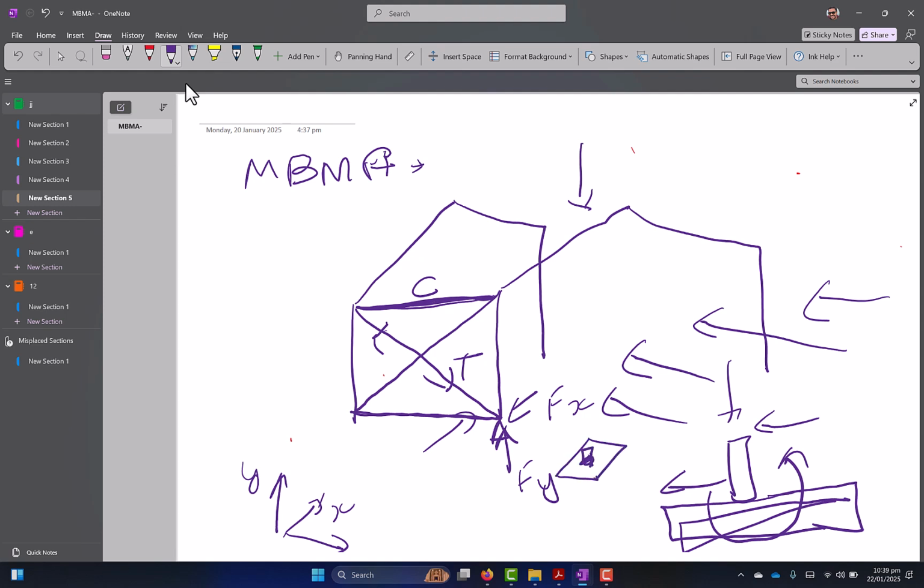Most of the time these are pretty much negligible if you look at the wind loads being applied. So the plinth beam over here will have zero contribution in the resistance of the gravity load or the Fx and Fy. Fz is resolved by the tension-compression phenomenon, and it just comes here. It creates a little bit of turning, but this beam does not do anything.